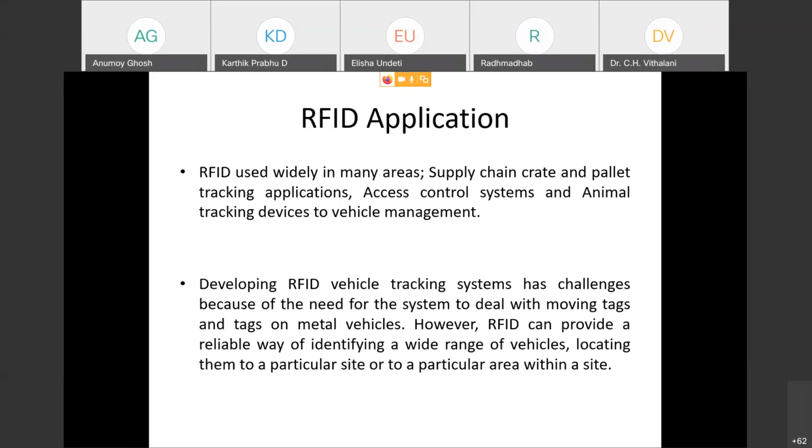And how to deal with these very fast moving tags, how to deal with this short interaction time? As I have told you, there are two design criteria of RFID antennas. First, the reader should be circularly polarized. Second, the tag should be omnidirectional. Here comes the essence of why a reader should be circularly polarized.